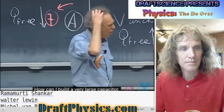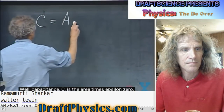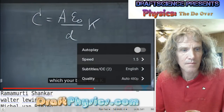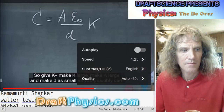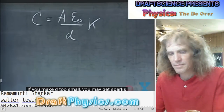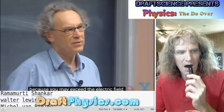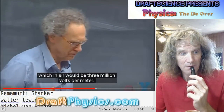How can I build a very large capacitor, one that has a very large capacitance? Well, capacitance, C, is the area times epsilon 0 divided by D times kappa, if your book calls it K. So make K large, make A large, and make D as small as you possibly can. Yeah, but you have a limit for D. If you make D too small, you may get sparks between the conductors, because you may exceed the breakdown electric field. So you must always stay below that breakdown field, which in air would be 3 million volts per meter.